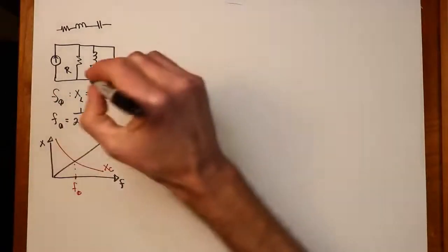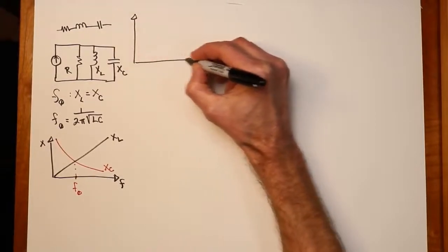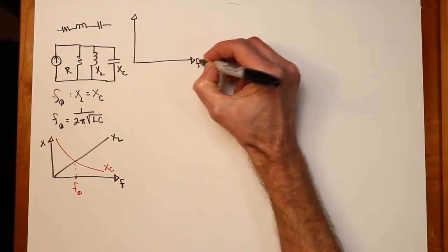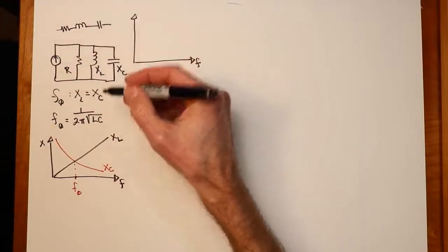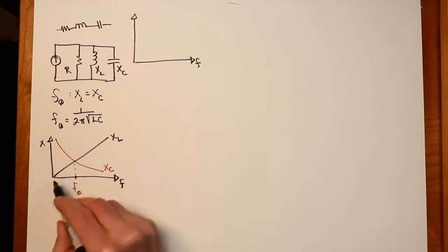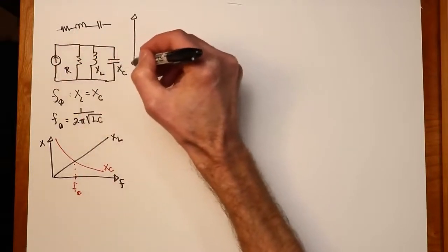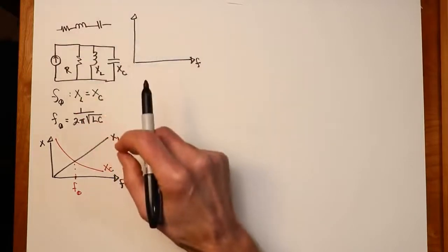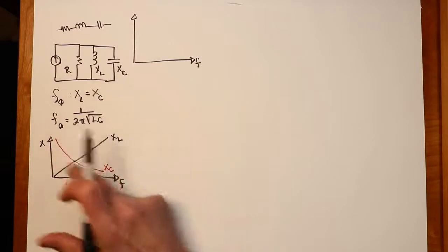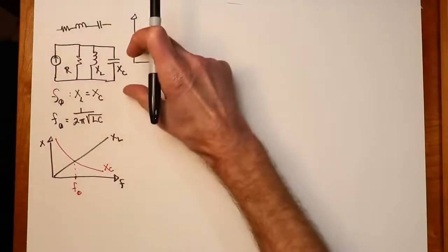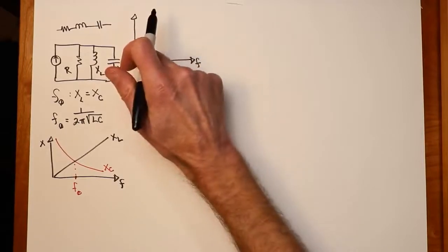With this, we see the opposite situation. Because they're in parallel, what ends up happening is at very low frequencies, X sub L is a small value. So it essentially shorts everything out, and we get a small value rather than a large value as in the series case. If we then go to the high frequency end, we see the same thing happening with X sub C. That basically shorts out everything. So we have a small impedance over here, small impedance back here.